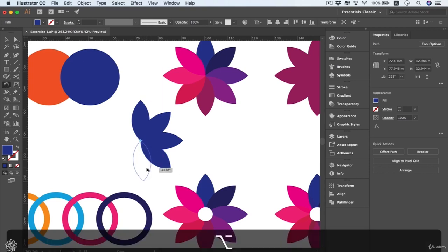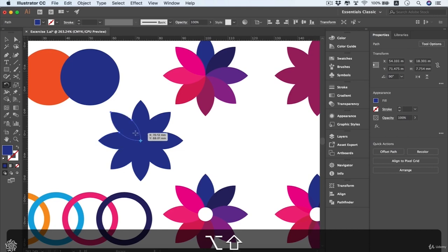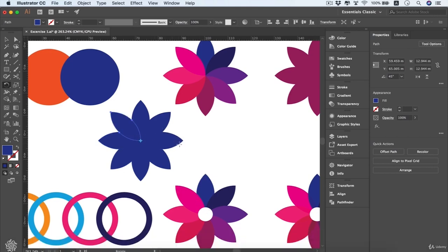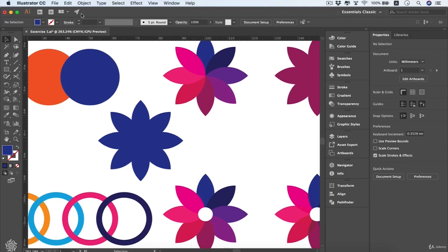And here we go, drag first, then Alt and Shift, and so on. So basically Alt is to duplicate any shape, and Shift is to get a precise angle like 45 degrees in here or 90 degrees. And now we've got a shape that is quite similar to a flower. We can start coloring that shape from here.